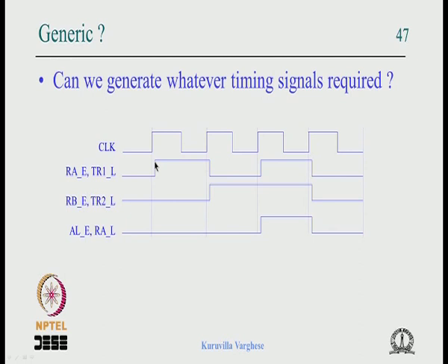So here you need a pulse in the first clock period and the third one. In the second one you need second and third, and in the third set you need in the third clock period. So as I said, it is easy. Say the first signal is nothing but the decode of 00 or decode of 10, and the second one is a decode of 01 and 10, which when minimized you get Q1 XOR Q0.